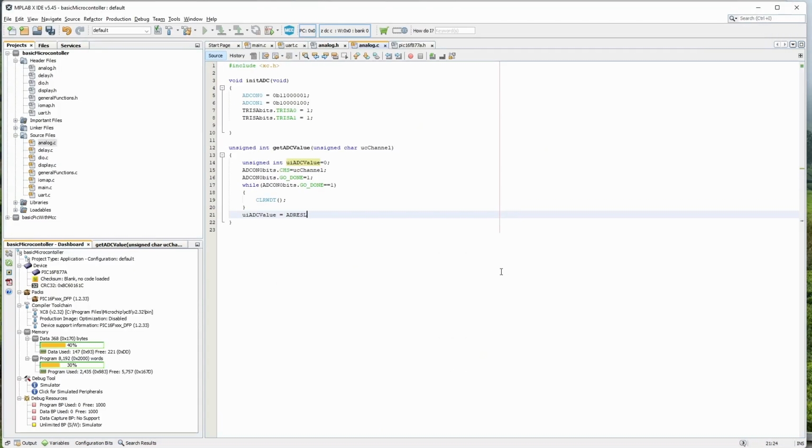You can again convert it into a 16-bit value and do bit manipulation. So just for the sake of simplicity, I will multiply by 256. That will convert these two registers into a 16-bit register. And I will return UI. So let me prototype this.